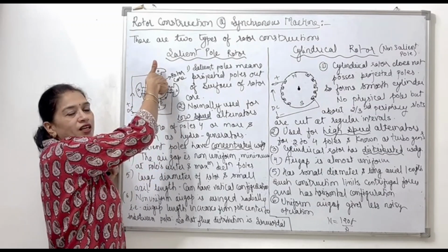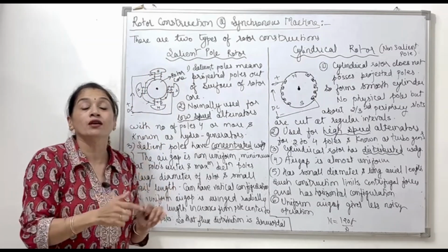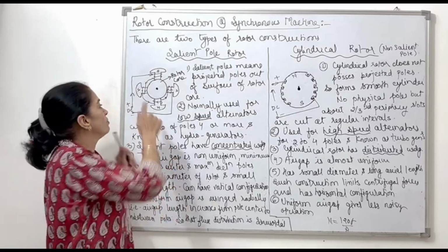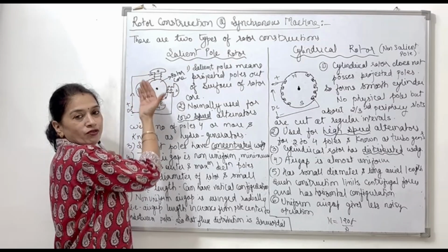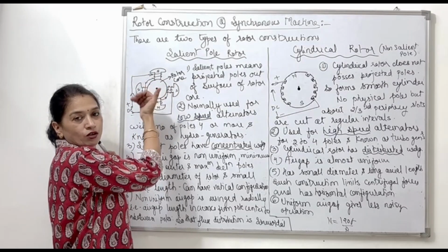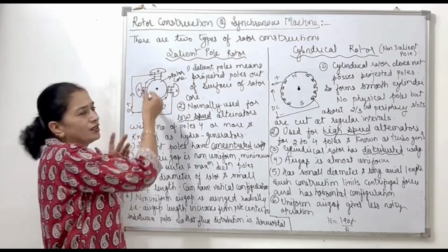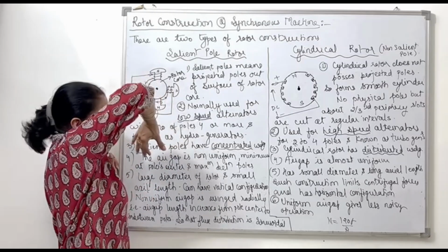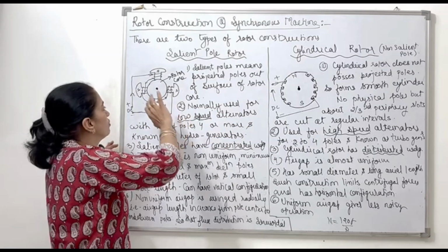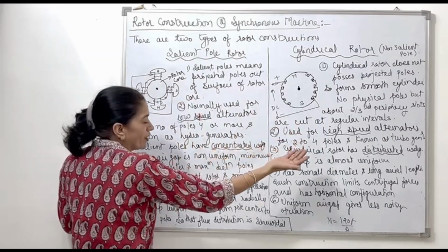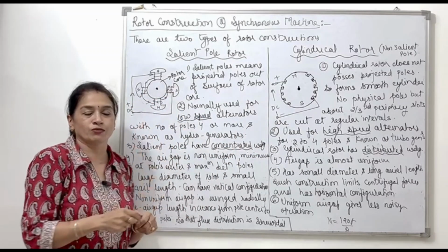If the flux is directed outward through this pole material, this is going to work as a north pole. Similarly here, if the flux lines are going inside, following the wrapping sense of my fingers according to the flow of current in the winding, it would generate a south pole. I made it in the same manner so that the current flows like this. So this becomes south pole, this becomes north pole, this becomes south pole.